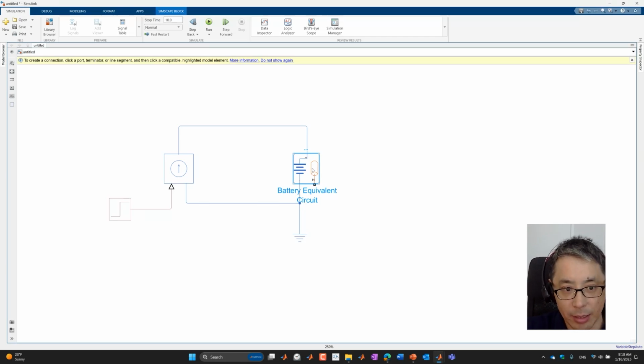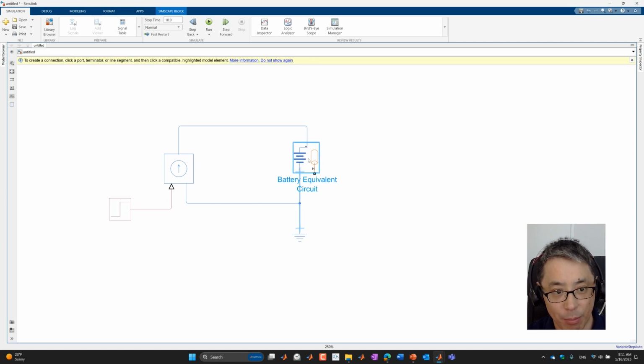And it does a pretty good job of coupling them, meaning how much heat is generated is calculated from the electrical domain, and then that heat generation is used as a source term in the thermal domain. Then the thermal domain will evolve the temperature, and the temperature will affect the electrical domain properties. So there's a two-way coupling between the electrical and thermal domains, all within this one block here.